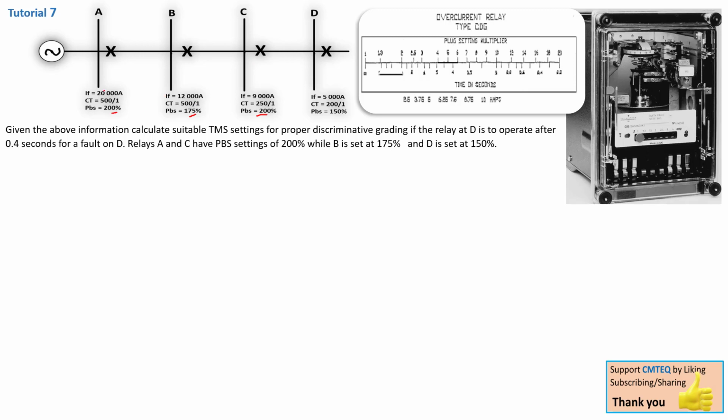And that will mean that the last relay here on bus bar A will have a much longer time before it's triggered compared to the previous relays. That prevents them all from tripping at the same time, or prevents this relay from tripping while relay C could have tripped just to protect bus bar D, putting the entire system offline. We don't want that. We want the system to remain online for as long as possible, obviously, while it's safe to do so.